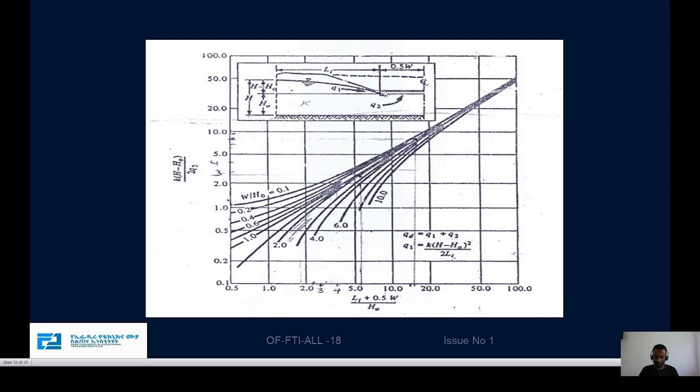This is the pavement structure, and the groundwater is at this level. At this level the water goes to the pavement, so we lower this water table and provide subsurface structures. This is given by Q1 and Q2. Q2 is the quantity of water under the surface, and Q1 is before reaching the pavement.